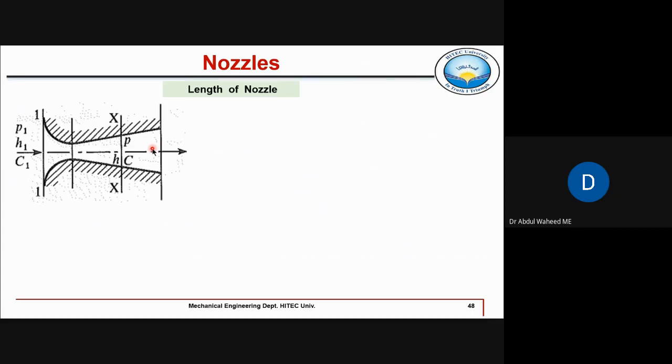And so when we are using a convergent divergent nozzle, it simply means the purpose of that nozzle is to attain supersonic velocities. It means this divergent portion will experience maximum velocity, and that's why the maximum frictional losses, because velocities are already in the supersonic region in this entire divergent section.